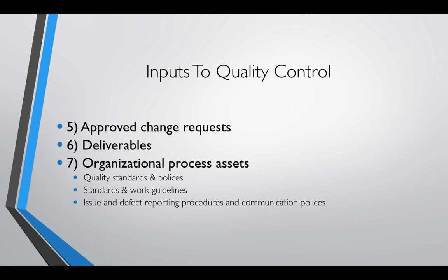So we know that on a horizontal type project, we would have the quality control team doing all these tests. If there's any specific test requirement called for that the quality control team does not possess, let's say they don't possess a welding certification, then the contractor would have to employ a third-party inspection agency, another inspection agency, to perform that type of inspection.